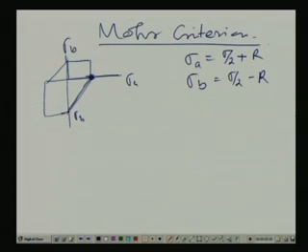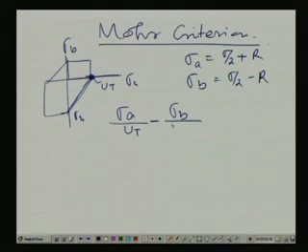And so the equation of the line is sigma A by UT, I am writing UT for tension, minus sigma B by UC, the compressive strength, the minus sign already being taken care of, and this equals 1.